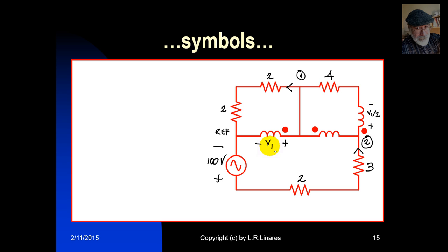And the value is going to be V1 divided by 2, since A2 is 2. And the voltage in the tertiary is going to have this polarity and this value, V1 over 3. So you see, instead of having 3 separate unknowns, V1, V2, and V3, we have only 1. What else? We also know there is a relationship between currents in primary, secondary, and tertiary.